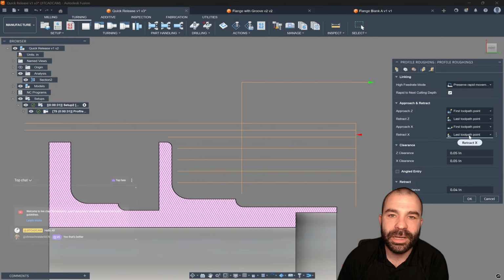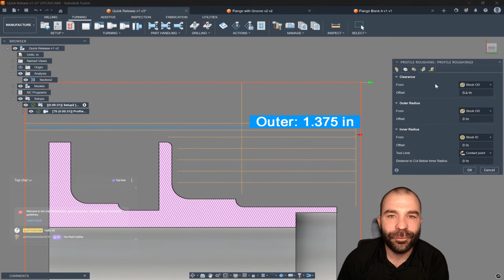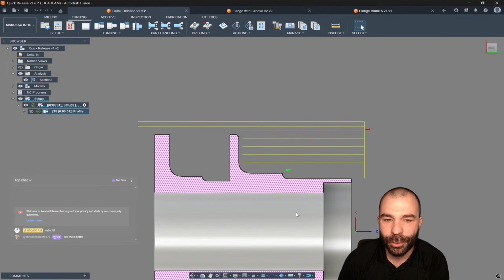One thing I want you guys to pay attention to, though, is you do have in here safe Z, and you also have clearance, right? Those adjustments will make a big difference, but they're still being driven, when you move further up in your toolpath, from clearance, for example. So just keep that in mind. We're going to go through a couple of scenarios why that would be important.